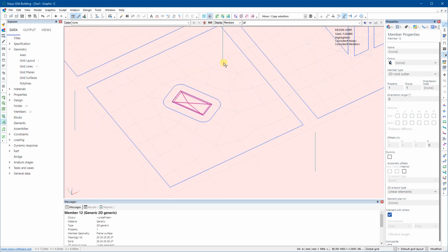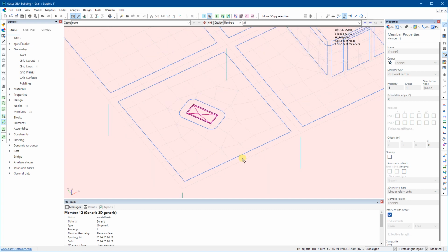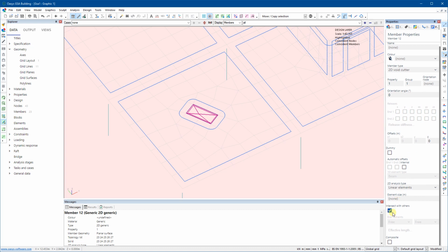Now these elements that you see in outline look all a bit big to me. Again, I maybe want them to be a bit smaller. So there's various ways of doing that. The way I would approach it, again, is if you come back to the right-hand column, there's an option to set the element size. So I'm going to say maybe 0.3 meters. And again, it changes it on the fly. But maybe I want it to be a bit.